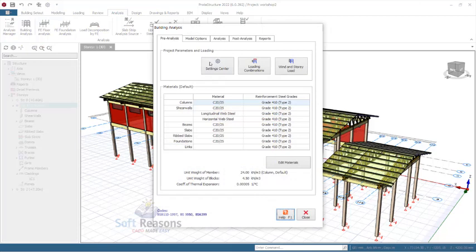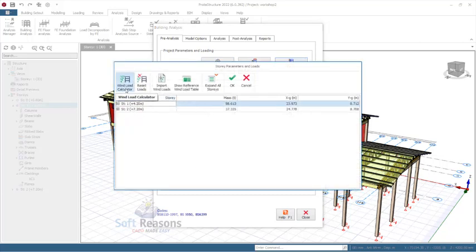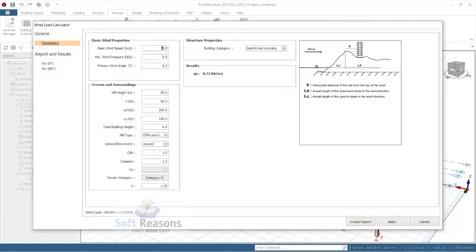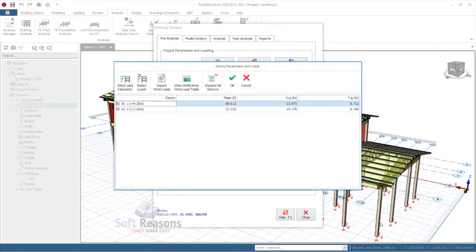So over here we can also look at the wind load. I tell you, we have to do some settings on the wind load. Okay, so click on this wind and story load, and then click on the wind load calculator provisions. So the wind speed over here is 35 meter per second. So you put here 35 meter per second, and then you can leave all of this at default. Okay, and then the building category is reinforced concrete building, so you just use composite. All right, so click on apply and then OK.